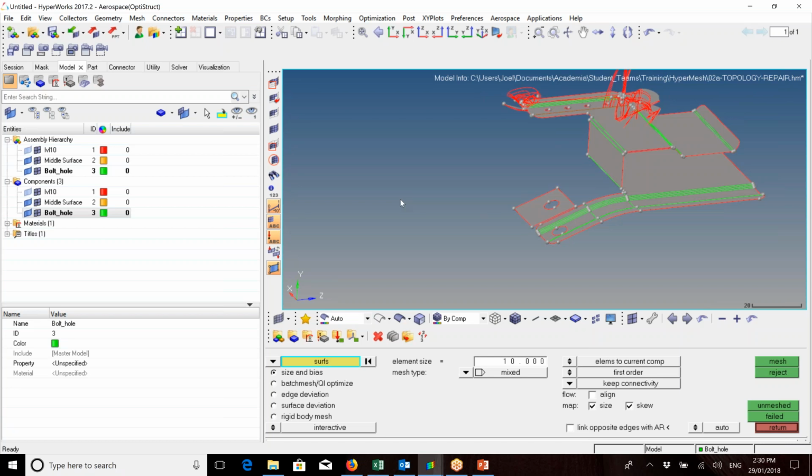No? Okay, so the difference between your first order and second order elements is the amount of integration points. If you were to draw a triangle on a piece of paper right now, each of those points is an integration point where you've got all the calculation performed. That would be a first order, same as a square. If you draw a square, the 4 points there are your integration points, and that's where your calcs are going to be coming from.